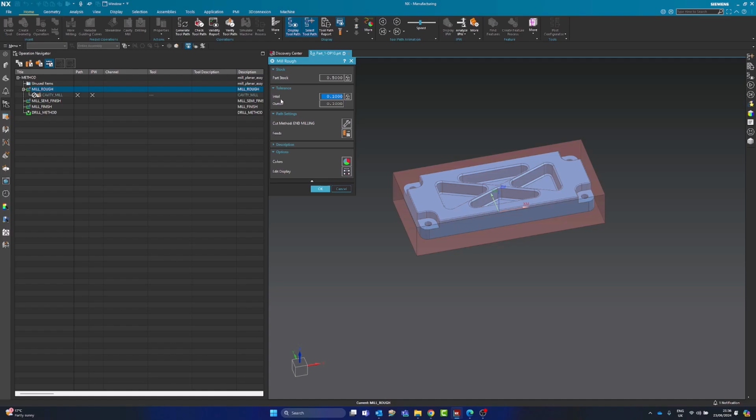So our intol and outtol, I'm going to say 0.8 and 0.8, which is fine. And this would just mean our toolpaths will generate a lot quicker. If we had a micron and a micron, our roughing toolpaths, I don't think they'd take ages, but they would definitely take 5x longer than at this level, maybe more. It would still generate pretty quick, to be fair, but the more roughing toolpaths you do, it compounds. It will get slower because it's looking at the resulting stock.